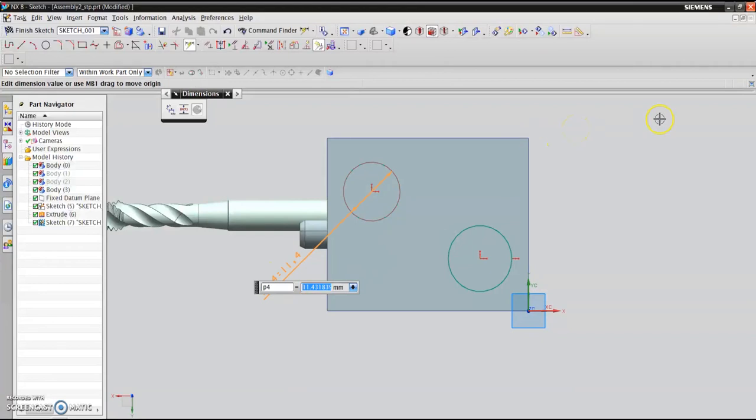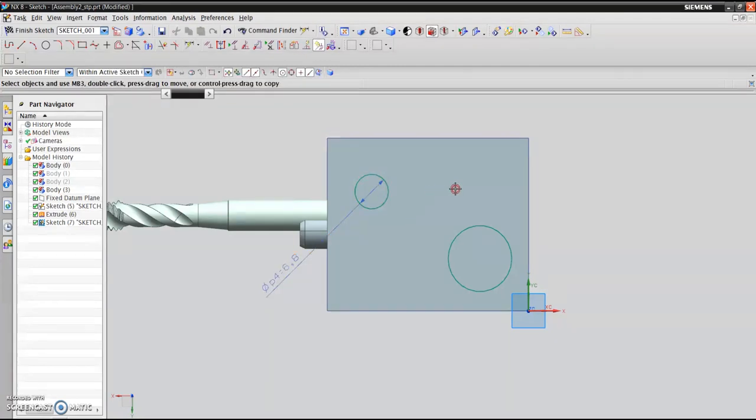Okay, so it's a metric M8 thread with 1.25 pitch. M8 is the major diameter of the thread. Subtract the pitch, 1.25, and you get 6.75, the nominal minor diameter that we need to hold. So that's the drill bit we need to select. Second, let's do the 10mm thread. That's M10 by 1.25. Again, M10 is the major diameter and 1.25 is the pitch. Subtract 10mm minus 1.25, and you get 8.75mm.